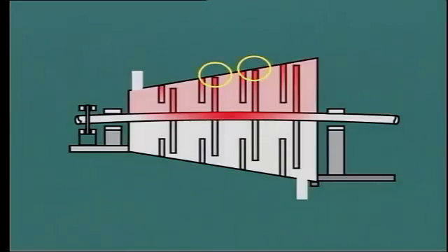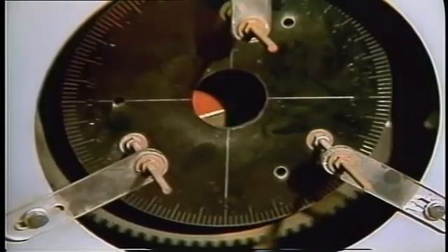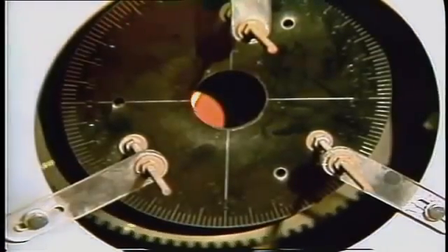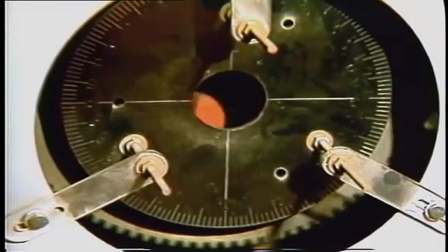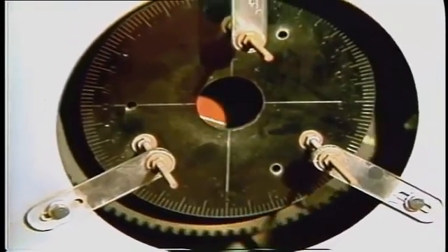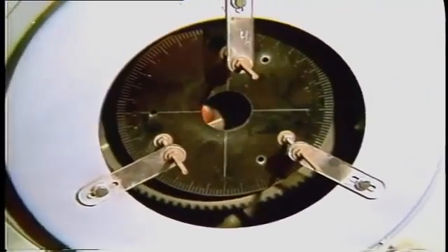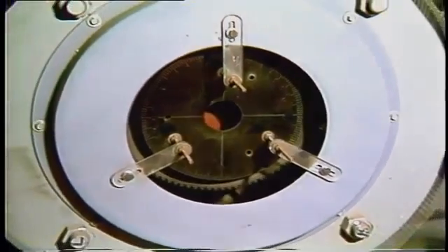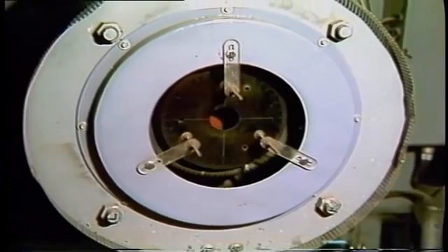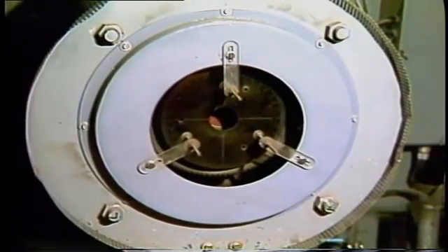To prevent this problem, it is essential that the rotor be placed on turning gear immediately after the unit is taken out of service. This ensures that the heat is evenly spread around the rotor and there is consequently no chance of distortion. It should remain on turning gear for several days at least if a long outage is contemplated. Operation of the turning gear after shutdown is so important that in the case of a failure of the equipment, say a motor failure, then drastic action must be taken.